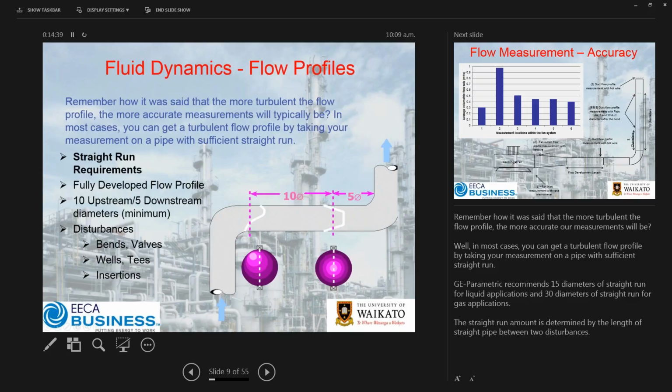Now, this is a very quick refresher for today, but it is important to remind ourselves that when we're measuring turbulent flow, the more accurate measurements are going to be in a straight section of duct. Okay, so you're going to get a turbulent profile, but we need to get a uniform profile. So as an ideal best practice measurement, if you're doing a laboratory controlled measurement, you actually want the best part of 30 duct diameters, 20 upstream and 10 downstream.